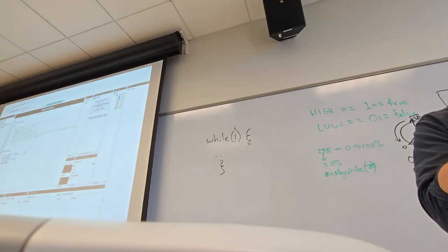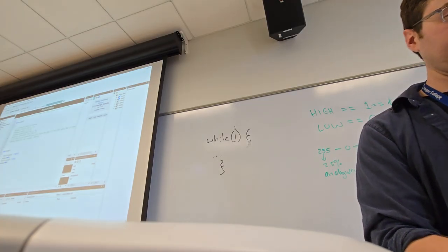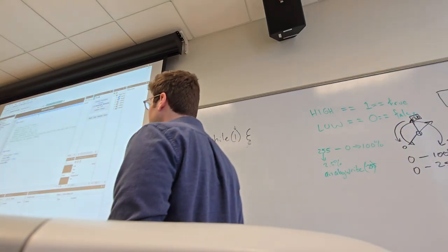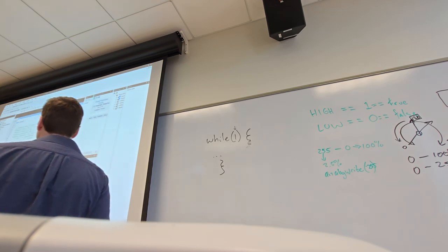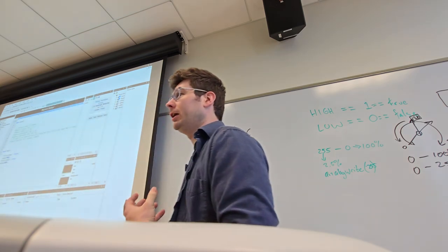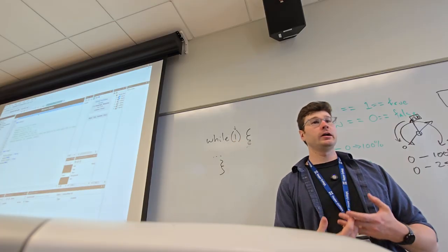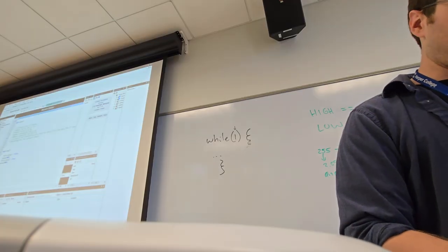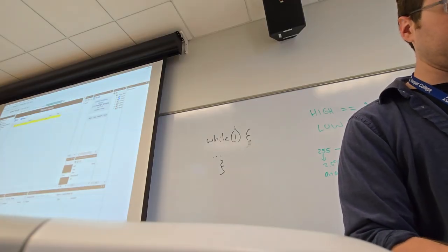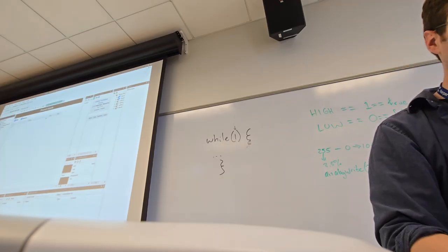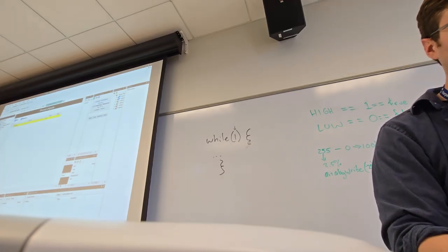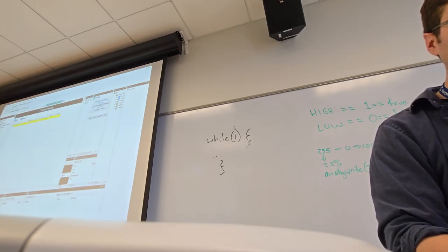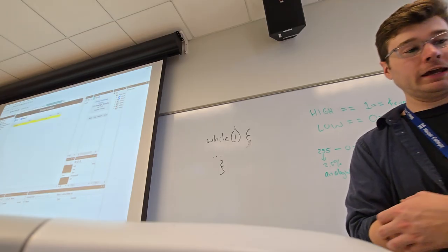The different thing is that there is a little bit of a handover. There's a shared access between the PLC side of things and the Arduino side of things. There's information exchange, there's handoff. The two processors have to talk to each other and sync up at some point in time. That handoff, or what data is exchanged, is handled in the shared inputs and shared outputs category.